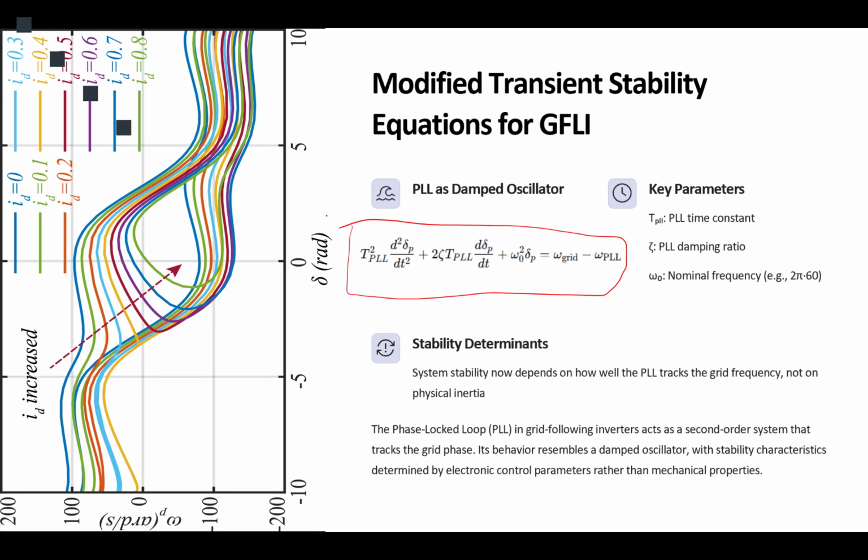Now, the psi that you see in our equation is the damping ratio of our PLL. You remember when we talked about the PID controller? The damping ratio was the ability of our PID controller to reduce the errors to get to the new steady state. So that also could represent the same damping factor. It's basically literally equal to the damping factor that we had in rotary machine.